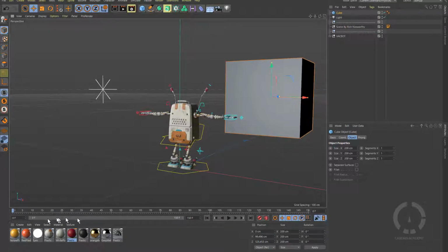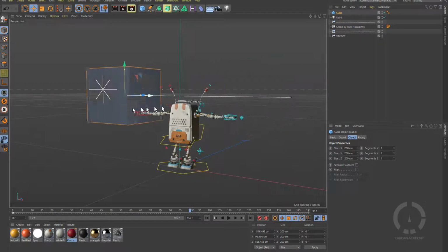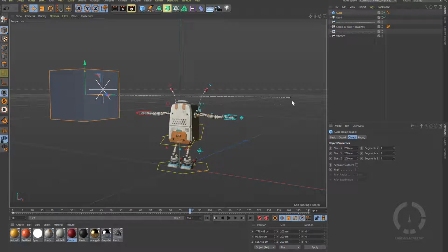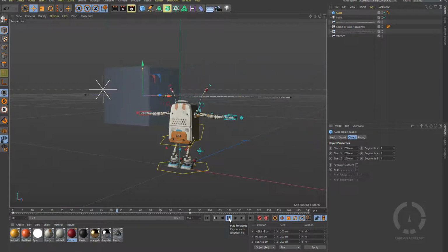Now, for example, if you want to see what we can do with this little guy in here, this is meant for animation. If I want to animate this cube, I can put it in here, let's say, and I'm just going to create a keyframe. Don't worry about this. I'm just going to press Control and click in here, and then I'm going to go to frame 90. All right, and I'm going to move this guy to this area, and I'm going to press Control, click, and now I created an animation. You can see this line that is representing the animation that we have. Now here we have some controls where I can rewind this, and now this guy is going to go back to the starting position, and then I'm going to hit play, and now you can see that the cube is moving. It's magic. That is what is happening, my friends.